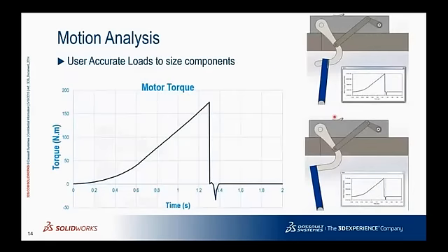If we take a zoom in look at that motor torque, there's a little negative spike here. That's because when it gets to the tip, the force is acting on the other side of our pivot, so it's actually trying to make it rotate faster than what the motor's rotating it through the gearbox. But the torque curve really is important because from that we can work out what gearbox we need hooked up to what motor to deliver that performance.